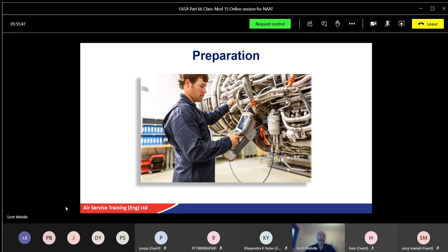Other factors, before you go and open all that up, you've got blanks around the engine for the inspection blanks. So let the engine cool down, okay, dissipation of heat. Watch out for windmill. If you're outside, the engine could be spinning over. So before you put anything down, you'd better put the blank on to stop the engine spinning.